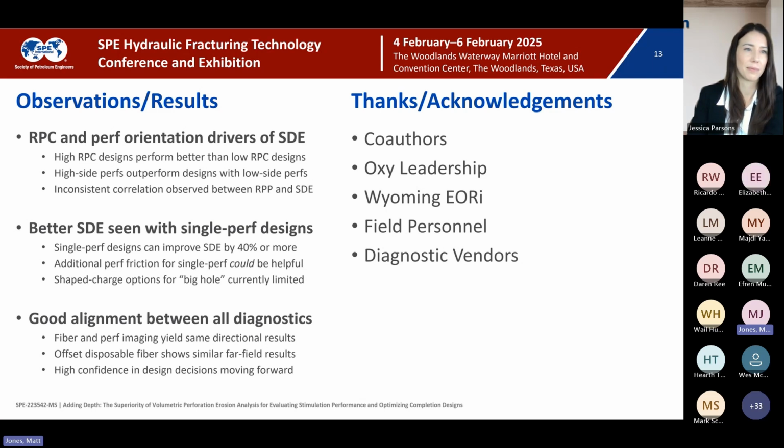And this is really one of the reasons why you want to look at a diagnostic technology like acoustic perf imaging. It's very high reward, high risk. You're going to spend a lot of money to install the permanent fiber optic cable. If everything goes according to plan, you get really great data both during stimulation and production. If you break it, then some of that information unfortunately goes out the window. Again, there's other things you can do. You can do conventional PLT, but it's quite expensive. It requires a downhole intervention, and you have to do it multiple times to make sense of the data.